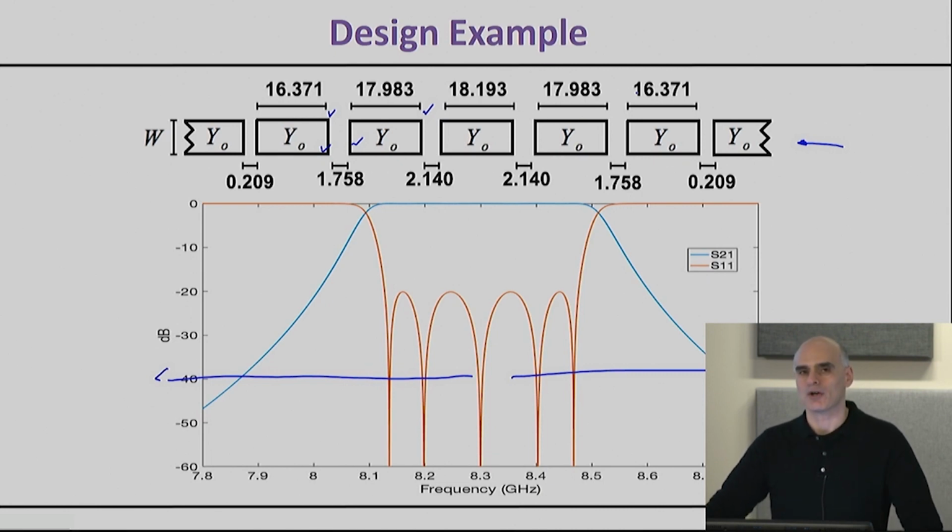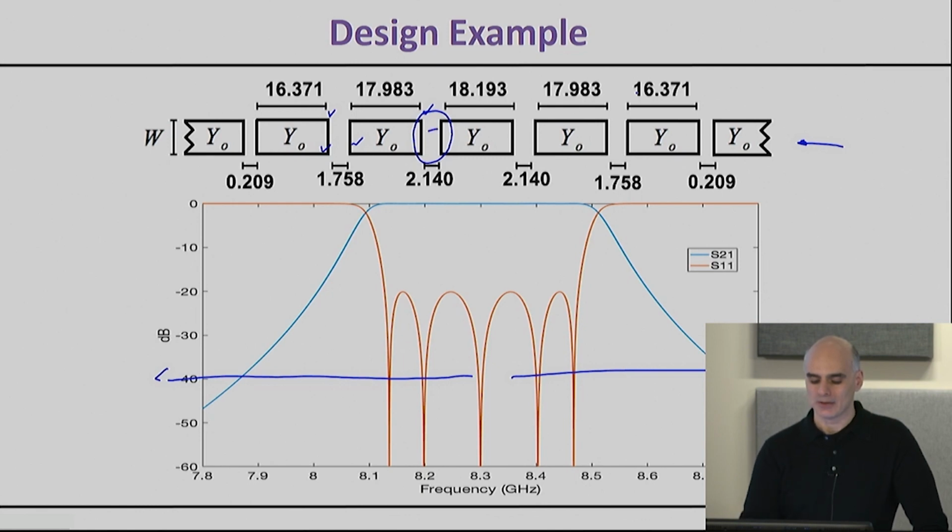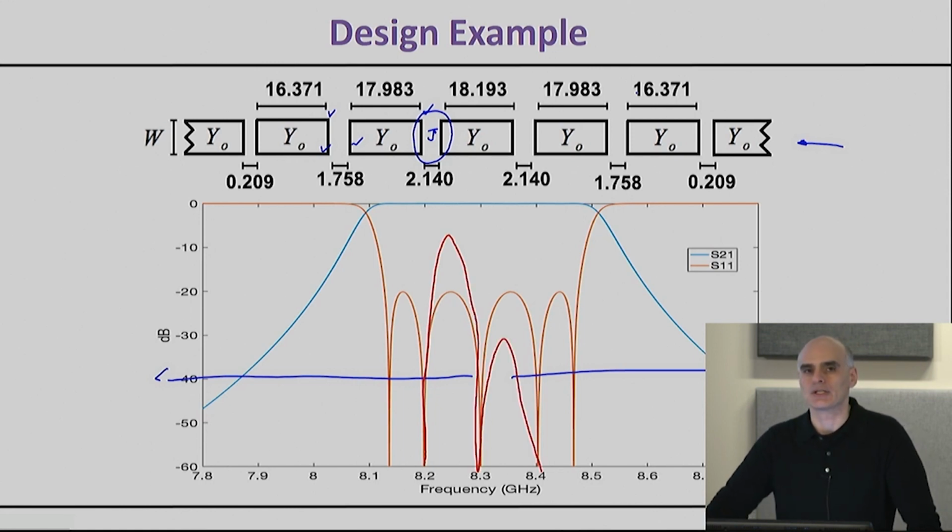The second thing you should be aware of is that currently we're using an approximation and relatively simple models to account essentially for the interresonator coupling, which of course is related to the J. In real life, when you lay this thing down, the exact layout will have uncertainties, it will have fabrication errors, and it's not going to work as ideally as you will see it here. Those type of things will show essentially as errors in the curve. For example, you might notice that some of the reflection zeros here will be misplaced, and you might have a little bit too high of reflection at some point.